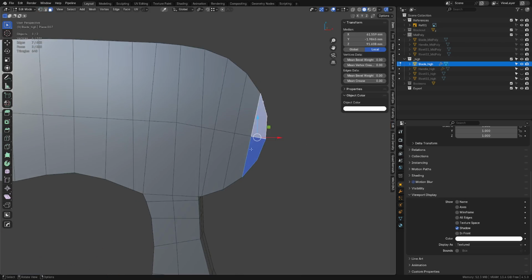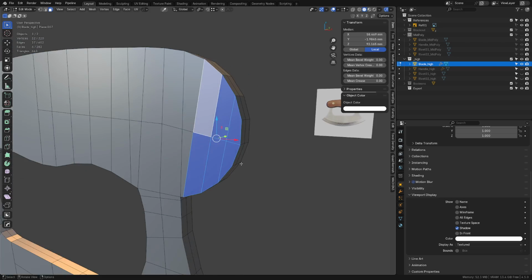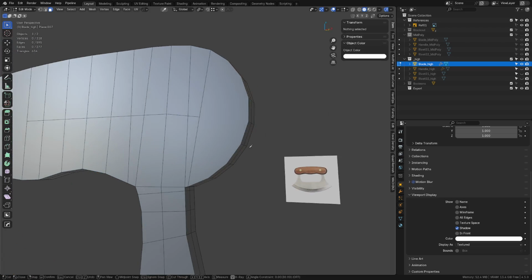Now, sometimes this causes weird topology, a topology issue anyways. I'm going to select all that and Control X it. We still have the center cut, but instead of doing them across from here, we can do them across from here and then cut these ones. And so we can split this whole section. Hold Shift and click and drag. You'll cut center points, right? Right click, hold Shift, cut and drag.